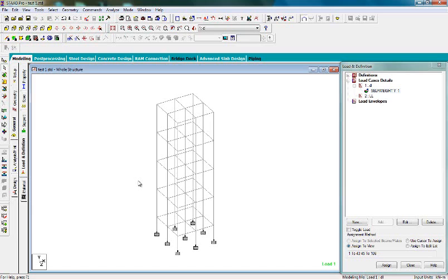After the self weight, there will be some loads like the loads of the walls coming all over the beams. Those are also dead loads: the loads of the wall coming over it, the floor finishing, the slab, these are all also dead load. We haven't added the slabs till now. So for that, DL, dead load only. Add,